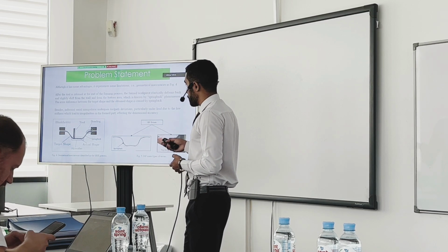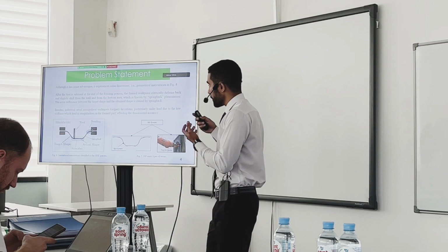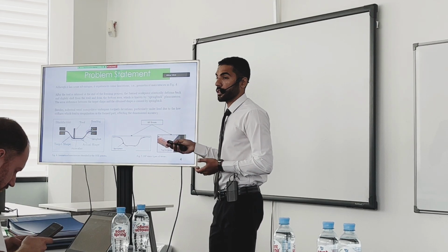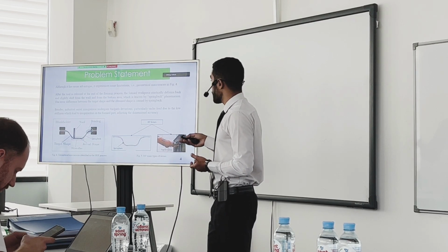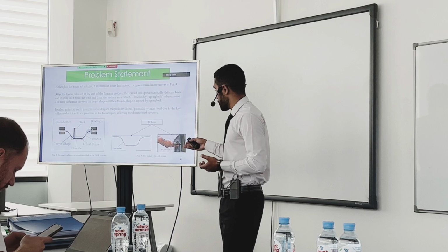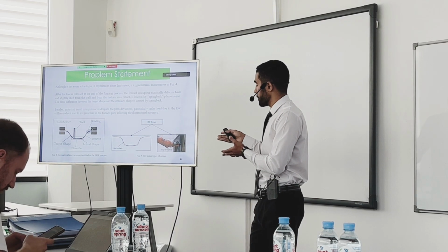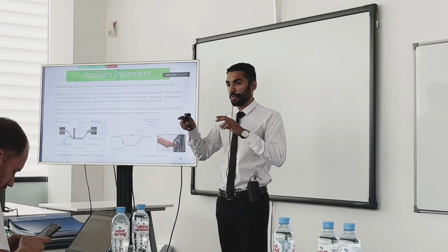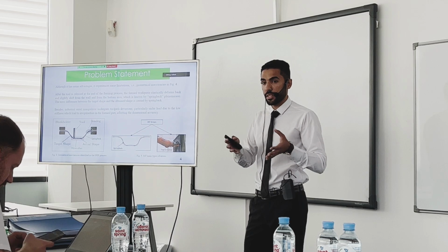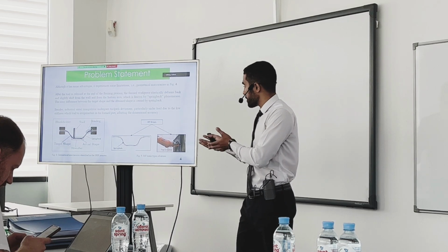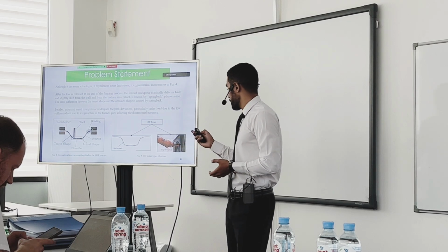There's also another part of the problems in this process, which is the use of industrial serial manipulators that are prone to accumulated error due to the low stiffness, which makes some tool-based deviations. I formulated the problem statement as follows. I split the problem into two main issues. The first issue is related to the material itself, which is characterized by the spring back effect. And the second issue is related to the robot itself, which is the tool-based deviation.